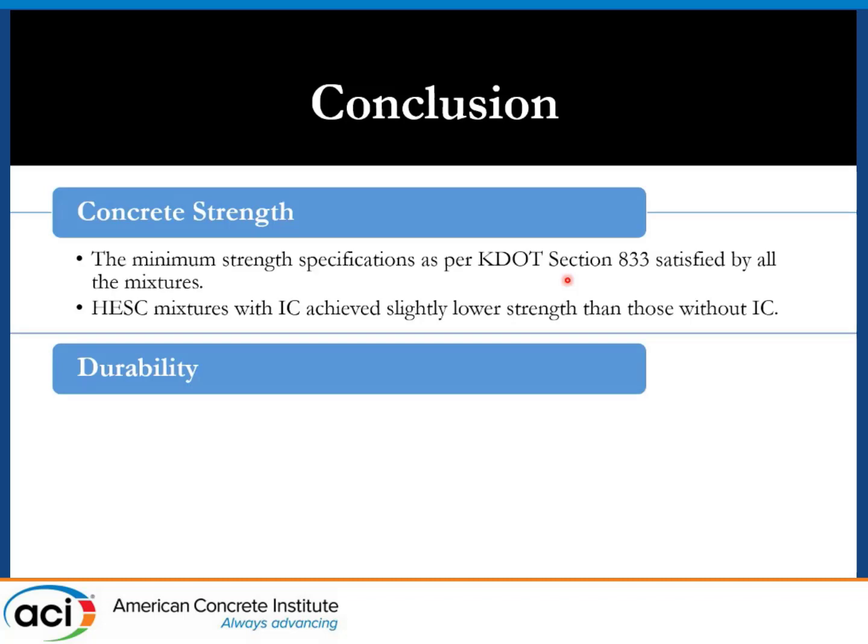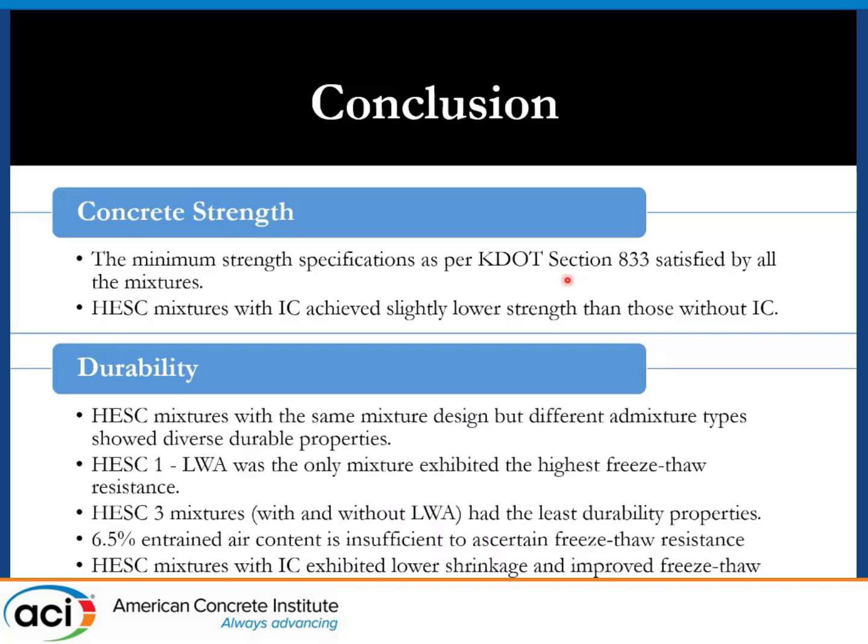So to conclude, we observed that the minimum strength specification as per KDOT section 833 was satisfied by all the HESC mixtures, although the HESC mixtures with internal curing showed a slightly lower strength than those without it. On the other hand, the durability properties of all the HESC mixtures were quite different from one another, even though they had the same mix design, same materials, and everything.